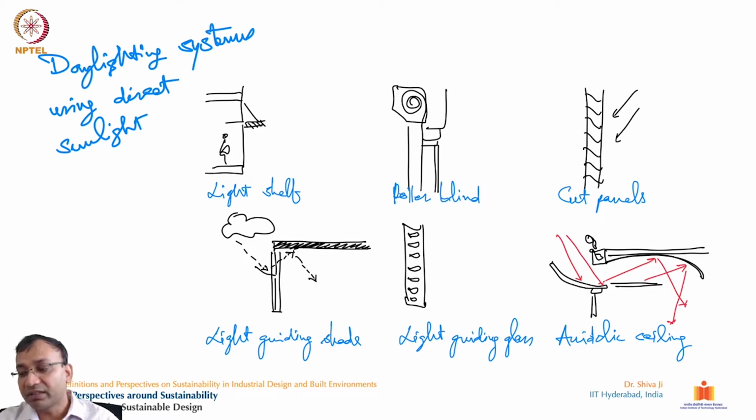In the summer the sun comes at the top, and in the winter it goes a little lateral, on the downside. So the penetration of sun becomes more in the winters, and it reduces in the summer. So we can use the width of this unit over here to control how much sunlight I want inside the interior of the space. This can be controlled over here, and of course with the number of fins in the windows.